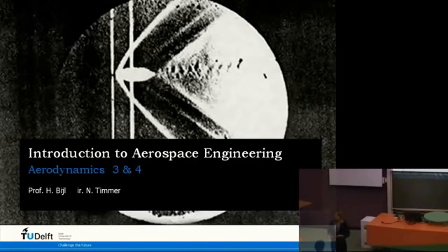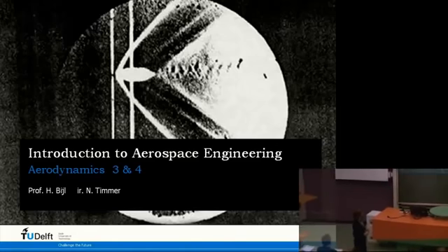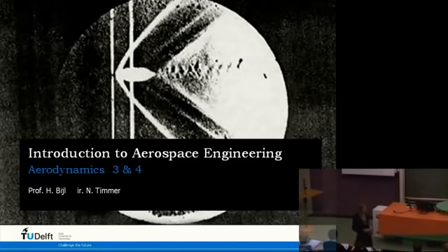We have, of course, the Euler equation in differential form, but can we get some more? And sort of a nice picture is the first picture of actually a shock. This is a shock in front of a bullet, which has a supersonic speed. And it is shown with a Schlieren image, which is used to visualize density gradients, changes in your flow.